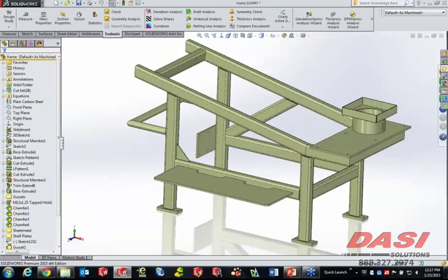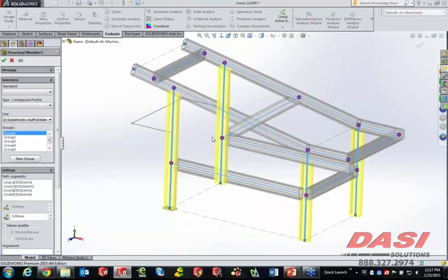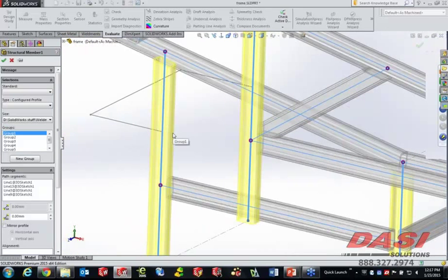Second thing I wanted to show you here actually had to do, and let's go back into that again, with a change that was made to our corner treatments. If we go ahead and take a look at this corner treatment bubble, and anywhere there's a magenta dot, not only in weldments, but also in patterns or sheet metal, those are points at which you can individually action on those particular locations, which means global settings aside, you can be very refined and detailed specific to the point we're selecting.